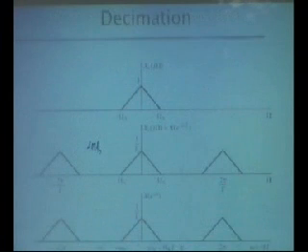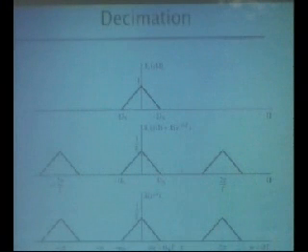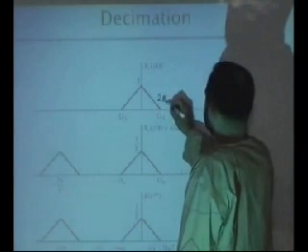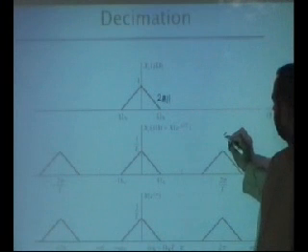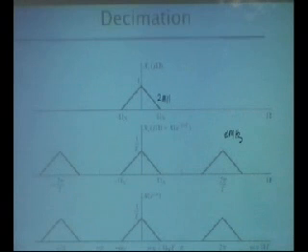these techniques. So here is an example. Let's say you sample a signal, this is a 2 megahertz signal, for example. Instead of 4, you sample it at 8 megahertz.